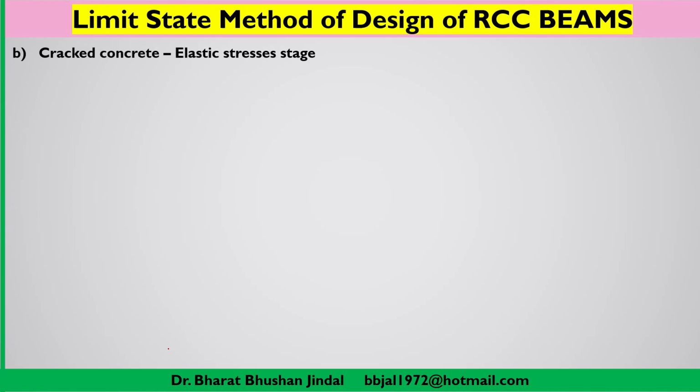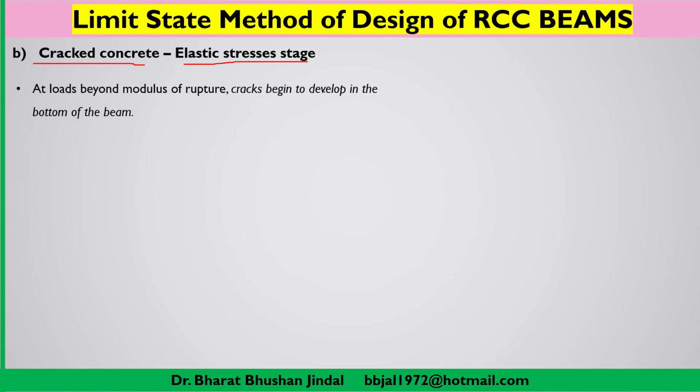Now, the second type of section behavior is cracked concrete, in the elastic stress range, within the elastic limit. As we increase the load beyond the modulus of rupture, what will happen? Cracks will begin to develop in the bottom of the beam. Bottom of the beam means below the neutral axis,